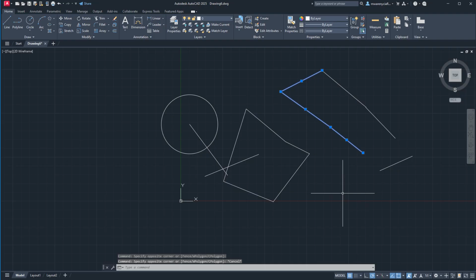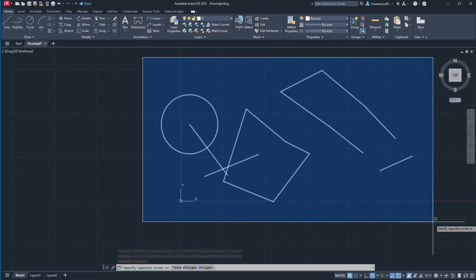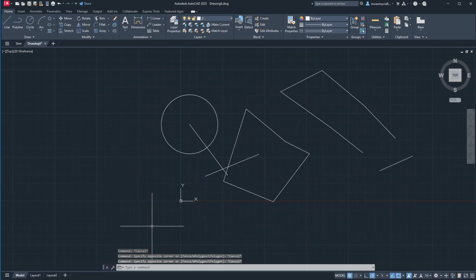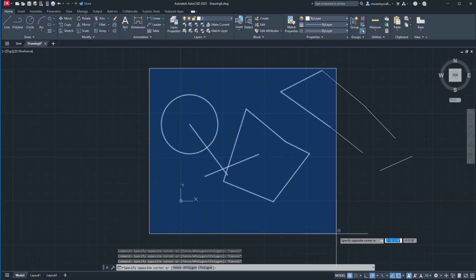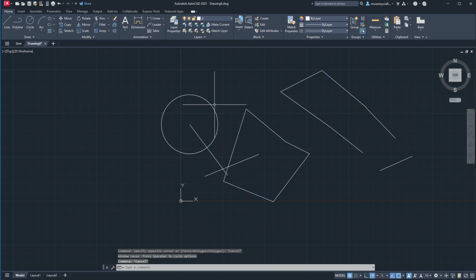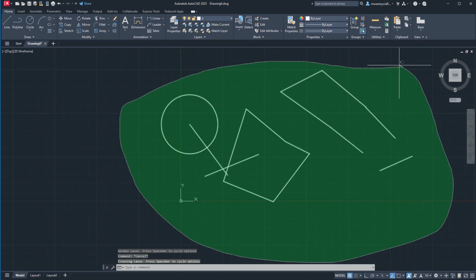Okay, let's talk about selection. You guys have seen me selecting things here. There's two main types of selection. There's left to right, which is going to use this blue area right here, and there's right to left, which is going to be this green. Just to clarify too, this is a click and then move the mouse, whereas you can click and drag and you get this kind of free-form shape. You can do the opposite direction and you will get the green shape.